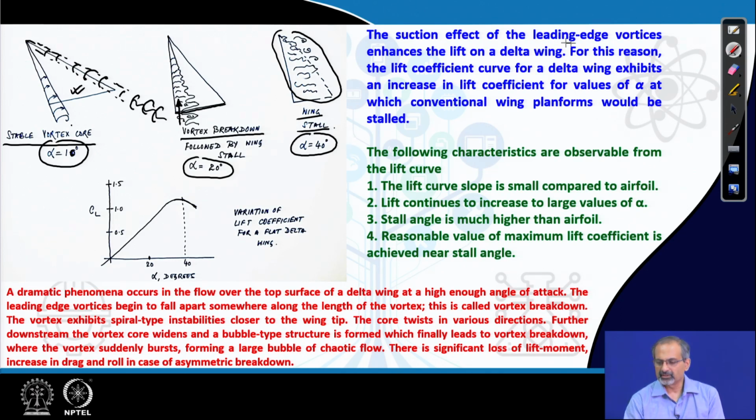So, the suction effect of the leading edge vortices enhances the lift on a delta wing, but in a situation like that of wing stall, it completely gets compromised.